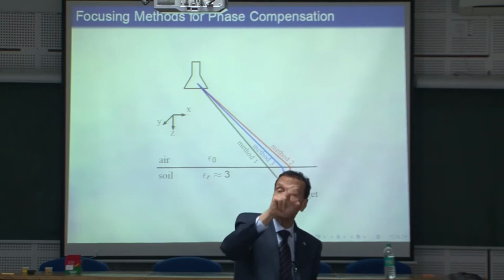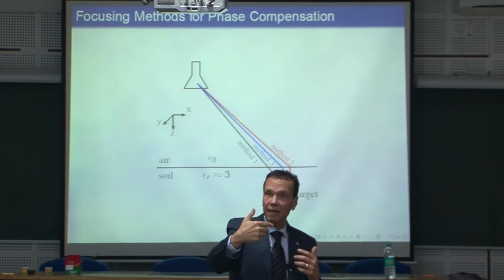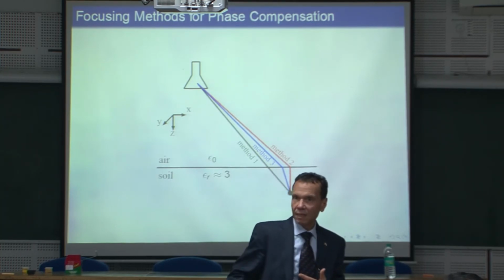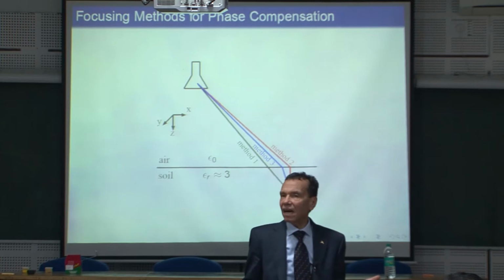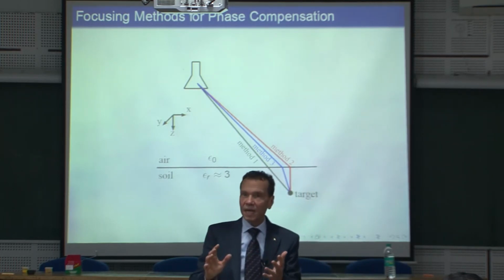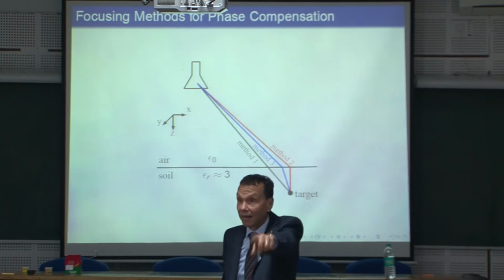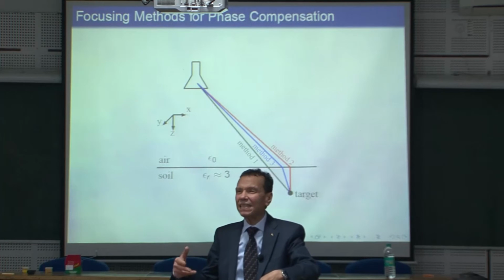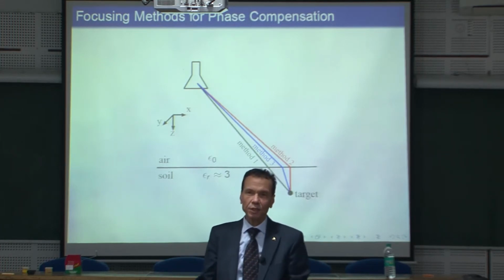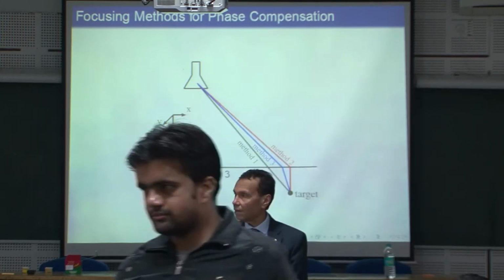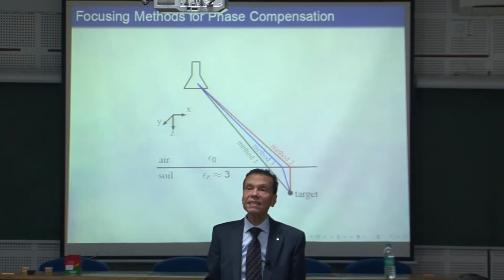And you say, okay, if I have something from this direction, the difference in the delays in these elements is, say, alpha. I will make it the other way around, so that when I add together, I collect maximum from here. Any other direction will be phased incorrectly, so that it cancels each other. This is the way you can understand the beam of an array, or you understand the focusing.